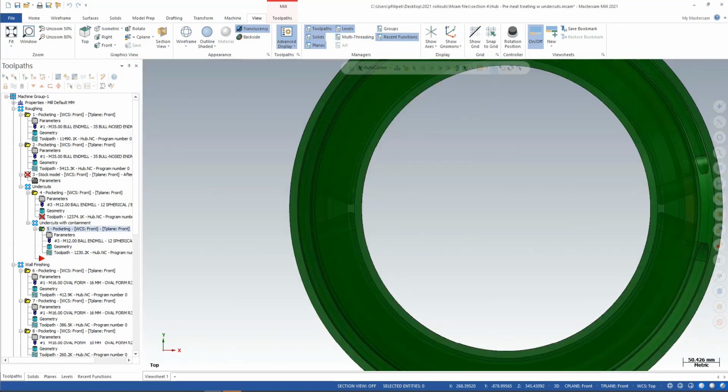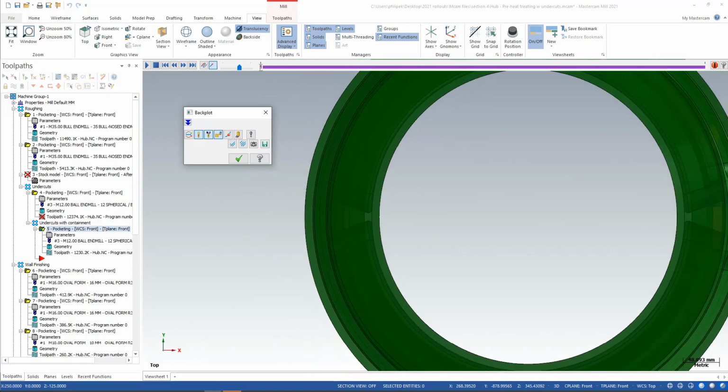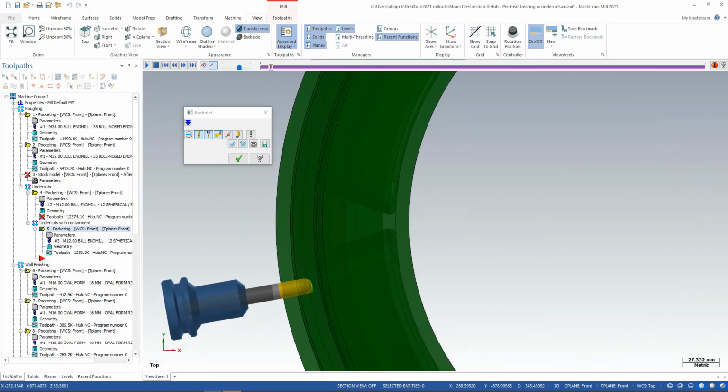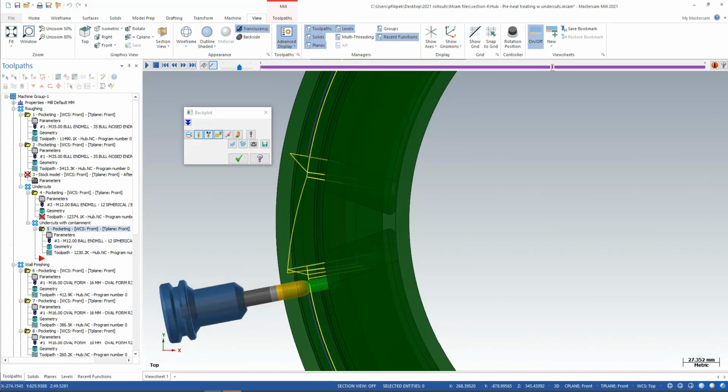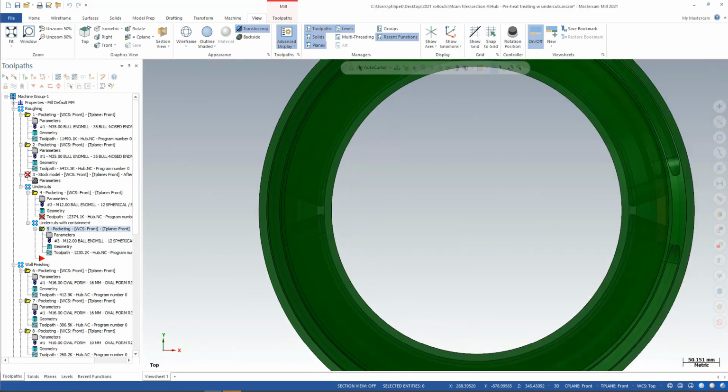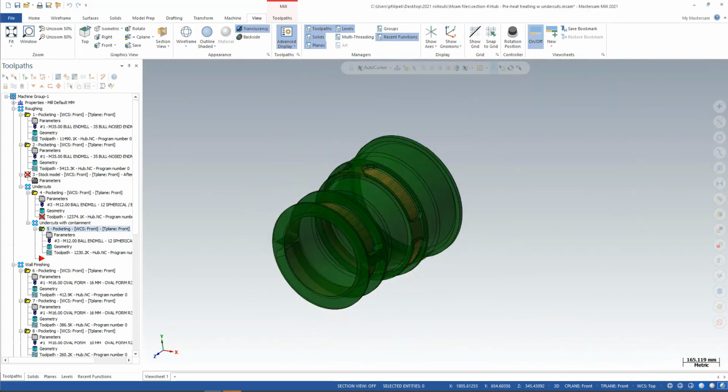Let's go ahead and take a look at this, and I'll show you on these pockets what this does. So it works in and then tilts to cut. Goes to the next one. Now it's cutting the top one. So we'll come back to this one here. Comes back, the next cuts in, and you can see it tilting. So I'm moving it back and forth. You can see the motion that it tilts underneath there to get the undercut achieved. So it's a pretty cool little function in that toolpath, the undercut options. Take a look at that when you're roughing. It's a pretty good one.